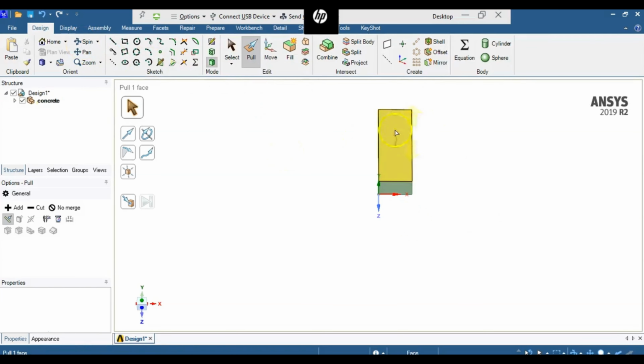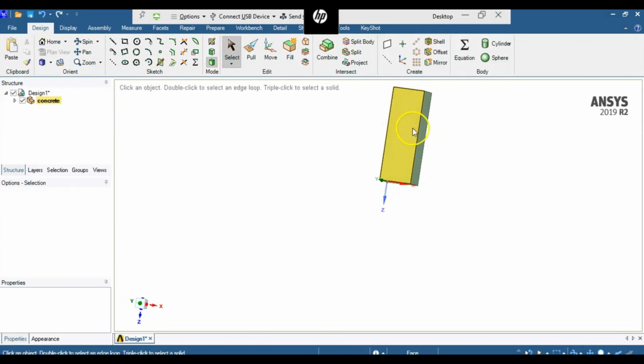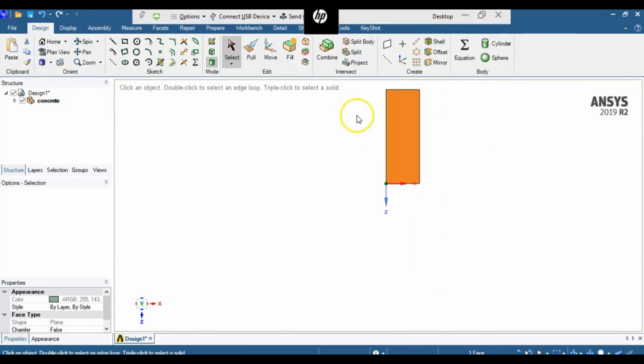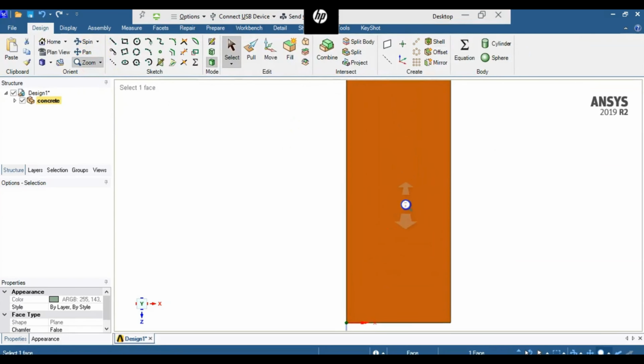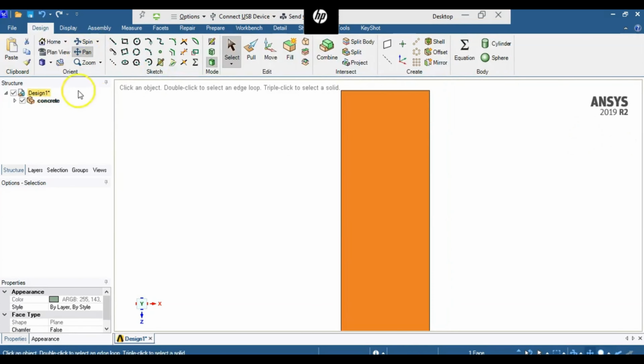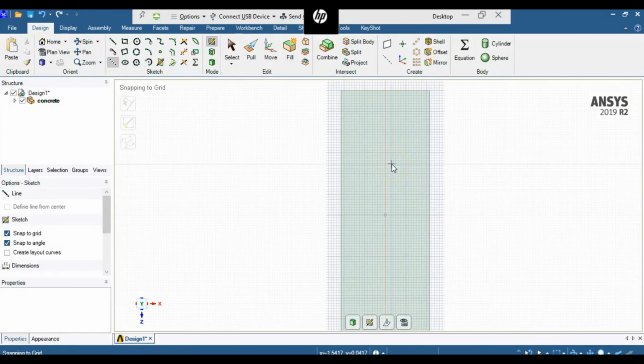Now we also know that there is a viewing window, so we have to create that space. Let's select this plane. The window is 0.5 feet from the top side and 0.5 from here. So let me draw a construction line just to identify the point.